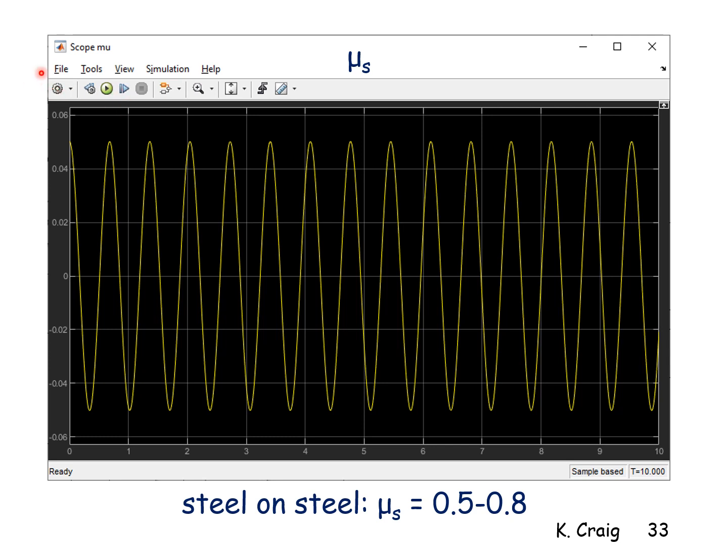Lastly, I combine the friction force and the normal force to then calculate the coefficient of static friction, which is the ratio of the friction force to the normal force. Over the range of motion during the oscillations, the coefficient of static friction needed for the no-slip condition is between approximately 0.05 and -0.05. So in magnitude, it's 0.05, which is much, much less than the steel-on-steel coefficient of static friction.